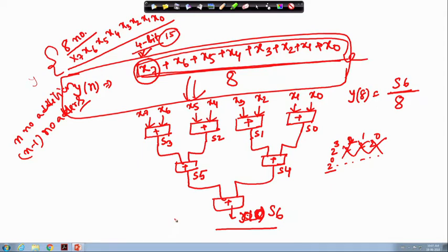Okay. Now, coming to the point, what does running average mean? Running average means these sets are basically changing. Where do I require a running average circuit? It is very much required for real-time signal processing. In real-time signal processing, the samples are changing dynamically, that is, the number of samples is dynamically changing. So, the samples come like this: x1, x2, x3, x4, x5, x6, x7.